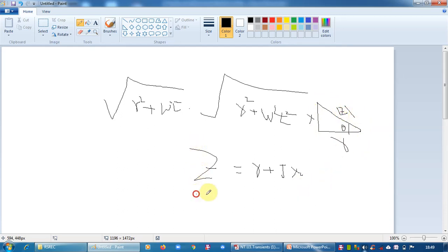What is the magnitude of Z? It equals the root of R square plus XL square. So in the impedance terms, the real part is resistance, the imaginary part is reactance, and the angle between them is the impedance angle theta. These components in the form of a triangle we can represent. This is known as the impedance triangle.